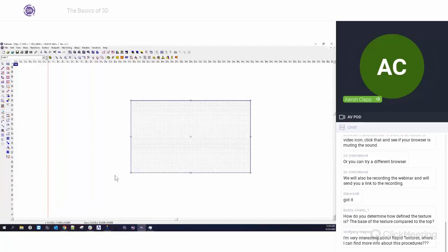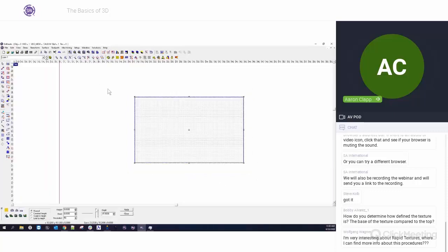The second thing that we want to remember is, depending on what we're doing, we can stack things on top of each other, but if we're creating a specific shape, we can set our constant height, our scale to height, or a limit to height, depending on the effect that we want. And then lastly, depending on if we're merging things together or adding multiple effects on top of each other, then we can start considering the subtract, merge highest, merge lowest, or replace relief. So those are your main things to take a look at.